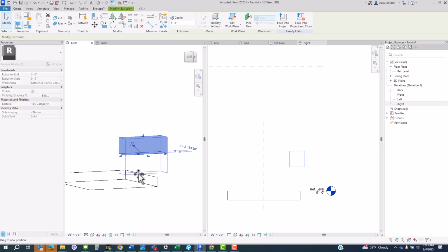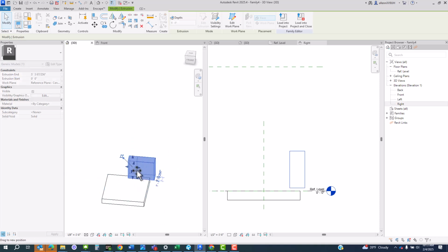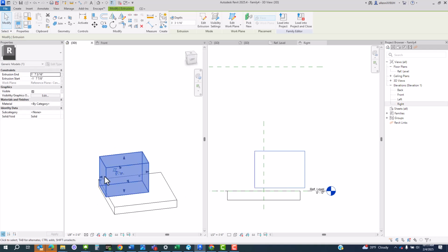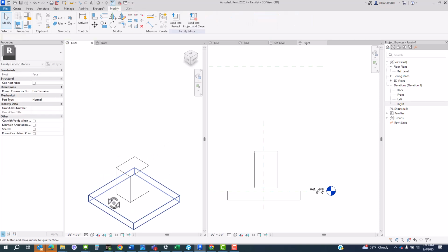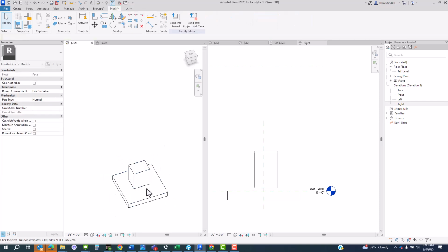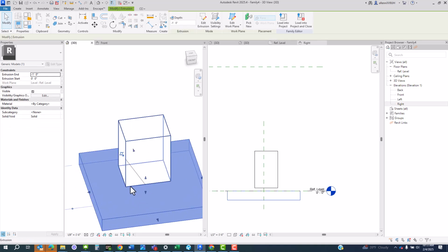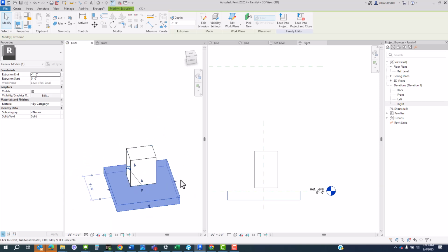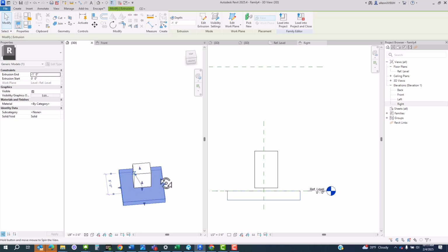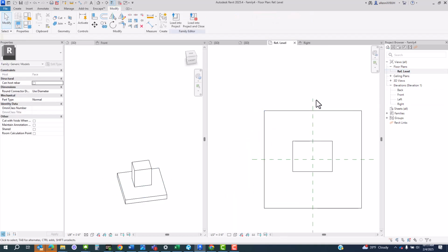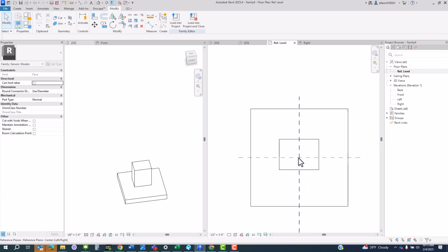And I want to point out the last thing, which is that the host is always the host. So no matter how many reference planes you create or adjust or show or set, the host is always going to be the host down here. Which means when I insert this, this will be the back of all of these forms. No matter how many combinations of forms there are, this area here will be the back of all those forms, and it will also be the insertion point. These original crosshairs form the exact insertion point, right where they touch.